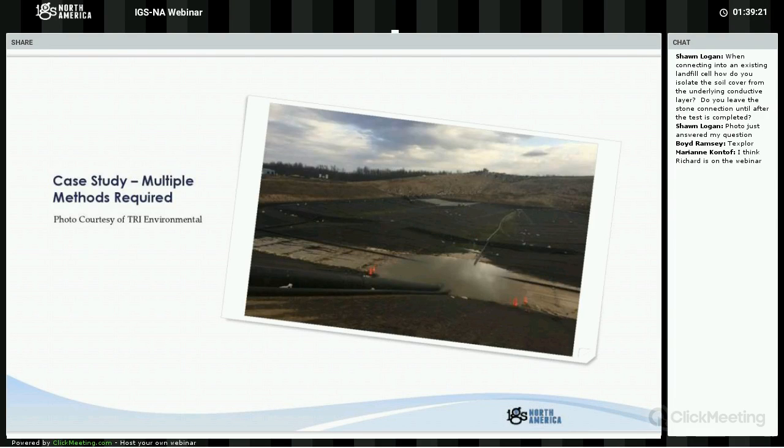Why did I use the arc testing instead of the water puddle method? Well, because I thought there might be a hole in here where the water is sitting, and if I had applied water using the water puddle up top, it would have just flowed to the sump where there could be a hole, and it would ground out my whole survey. So I would be hearing leaks everywhere I walked. So I wanted to do all the upslope with the arc testing method. I found three, maybe four holes using the arc testing method up there.